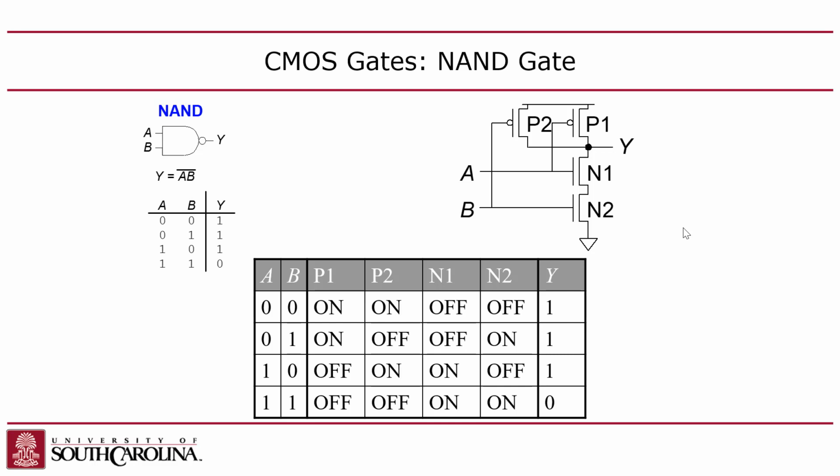But they're mutually exclusive. The output will only be electrically connected to ground or VDD, but never both. Well, I shouldn't say that. It is connected to both during the transient when you're switching. When I'm switching the input from 0 to 1 or 1 to 0, then they are actually both on briefly. You short power and ground during the switching, and that's where most of your power is lost. Make sense? That's called dynamic power consumption.